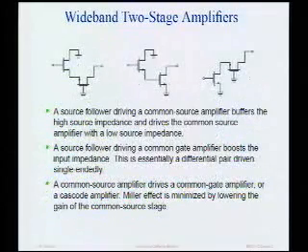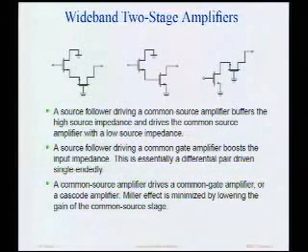Now, one way to fix these amplifiers is simply to go to 2 stages. And 2-stage amplifiers are very convenient, especially for integrated circuits, because transistors are really free. They're tiny. They take up very little area. So if you had to choose between a single-stage amplifier and a 2-stage amplifier, and area were a concern, it basically would not be a concern because transistors are so small in modern technologies. So we try to use more transistors to improve the performance of, let's say, amplifiers. Now here I have the first popular wideband 2-stage amplifier.